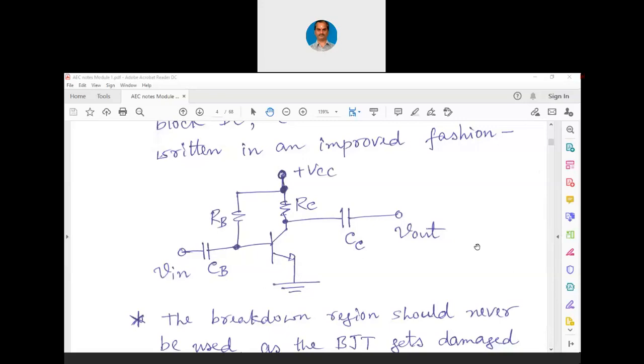In such a case, we need more stages of amplifiers where a picovolt or a femtovolt is amplified to millivolt or volt. That is when we connect one amplifier to another amplifier to another. That way, 3-stage, 4-stage, it is called multi-stage amplification. For that reason only, this is called a coupling capacitor. Meaning, one stage's output is coupled to the next stage.